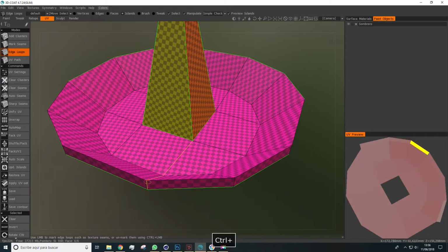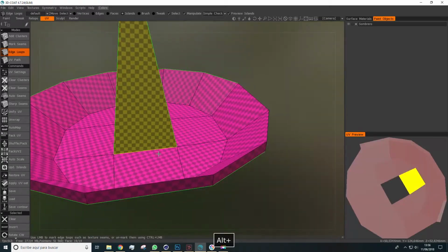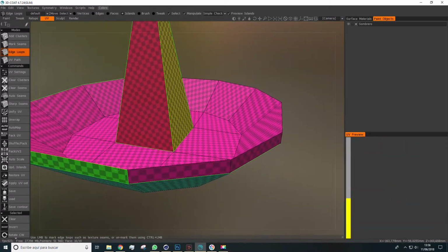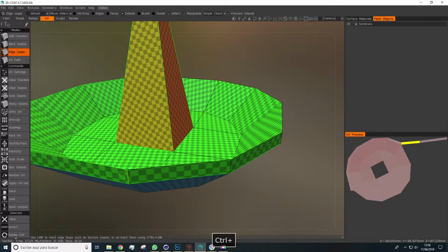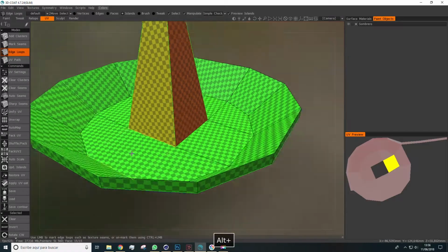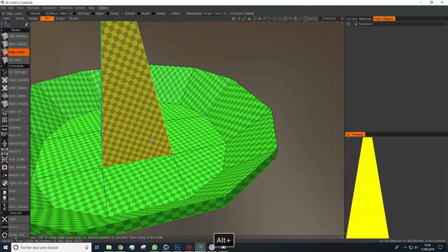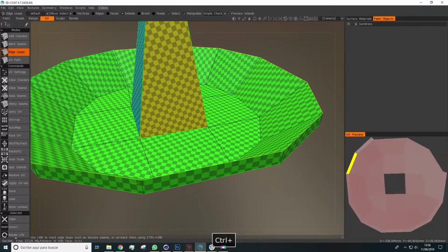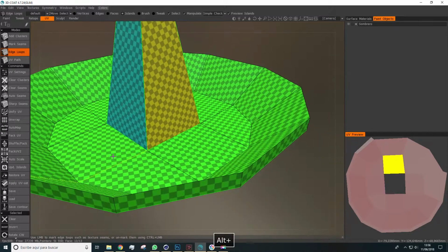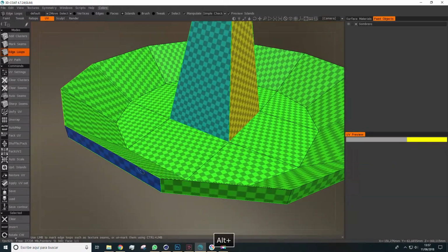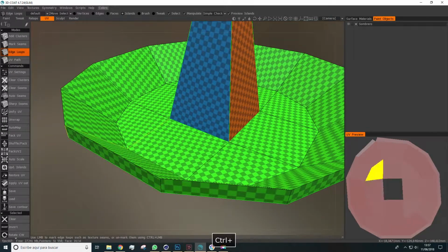Okay, so now I Control click this and I remove all these, okay? Notice that now I see in the preview that the UV map is better projected. Same here, there's another problem, so I do this, and we'd have all these in one texture. Okay, we remove all these. Check that there's no green spot. Here, for example, remove. And these two.